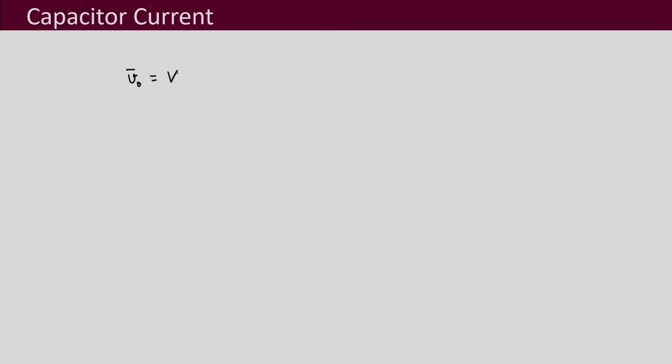Now, let us discuss the capacitor current. This is similar to what we had discussed for bipolar PWM. So, if we take the average over switching cycles, so if this is VO bar, VO hat sine of omega 1 t, and IO bar, the average current that you get over the switching cycle, sine of omega 1 t minus phi 1, and this is all ignoring the switching frequency components.